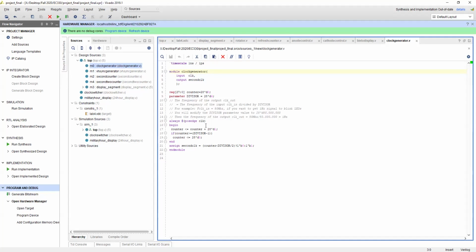So we're going to count up to 3. And every time we count 3, we're going to output that. Depending on whether or not the counter is less than that divisor determines whether or not we put out a power signal. So what this represents is we're cycling between 0, 1, 2, and 3. And then every time we hit 4, we reset back to 0. We're also going to output a signal since the counter is not less than the divisor divided by 2, since it is not 2.